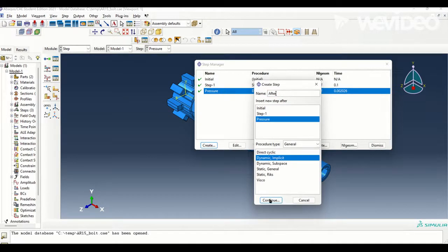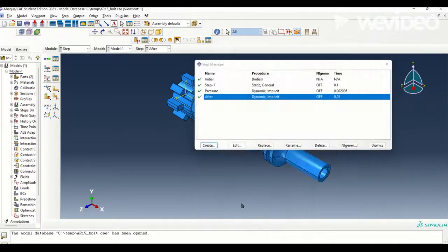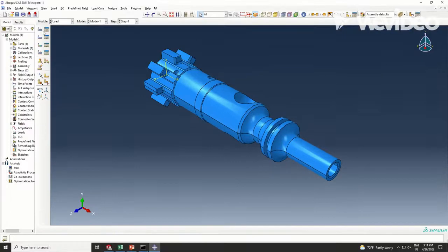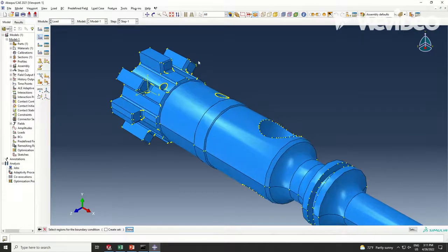After the steps, I then define the loads and displacements. The first displacement boundary is the back of the locking lugs. I then select the 7 back faces of the locking lugs on the bolt. These lock into the barrel extension and cannot move, so I imply that they cannot move in the X, Y, and Z direction, and then they cannot rotate. This makes them permanently static, as I am going to simulate they would be in the firearm.